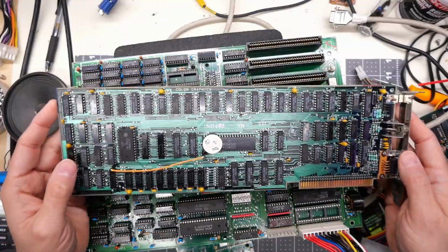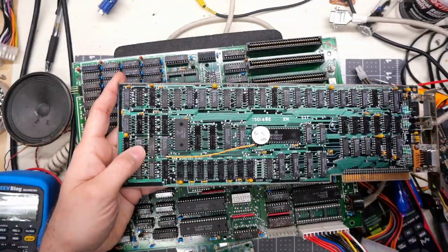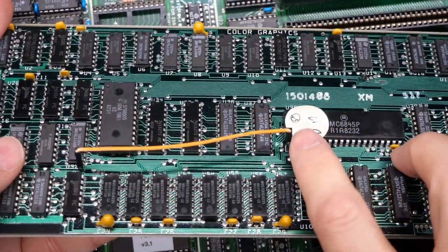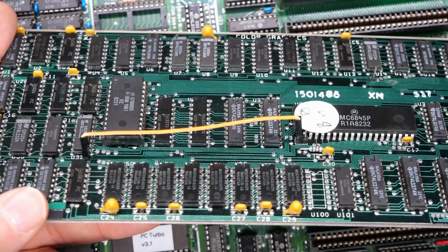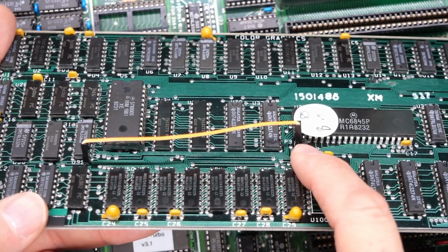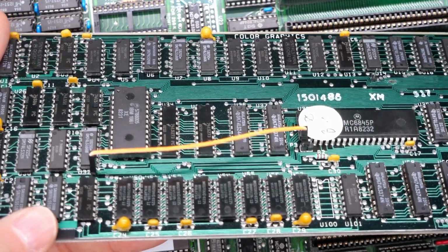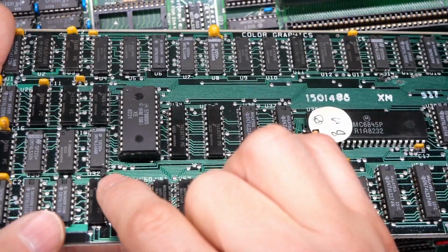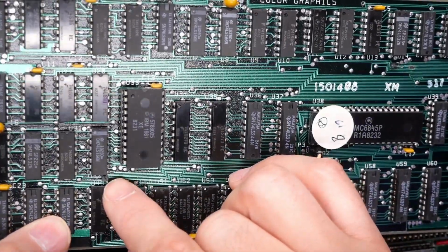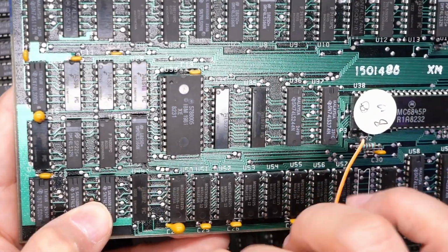Okay, so let's go over the mods one by one, just so you can replicate all of these mods yourself. So the first mod is the character or flashing mod. First thing you need to do is install the little 2-pin header right there at P3, which will allow you to put a jumper on there, whether you want to actually have thin characters or thick characters. The other thing you need to do is install a pin header there right next to the U92 marking. You can see where it is on the board there. You just have to clear that via out and install that pin header.